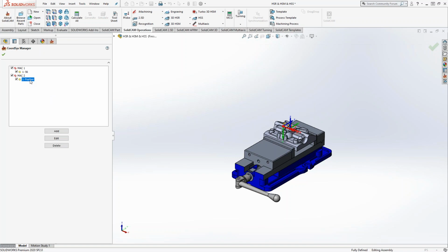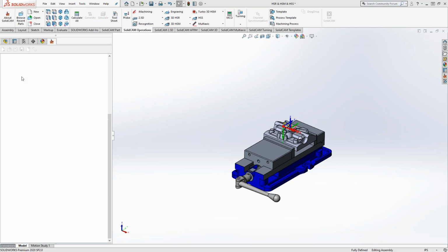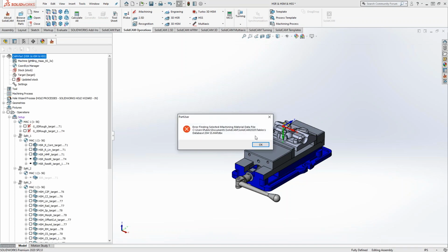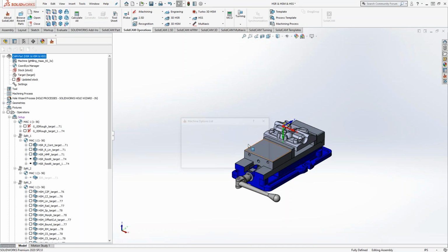Easy as that. In the newer posts, it's pretty simple like that. You just put in what you want it to be called. So if I want to automatically jump to G56 and I want my side 2 to be G56 as well, then you just relabel it. And to know if you can just do it like that, you can always go to your CAM part. And like I said, in the newer posts, that's automatically done for you.